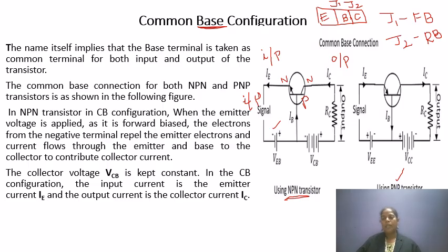The same thing. Here it is P, N, P, a PNP transistor. This side is the forward bias. Positive is connected to positive and negative is connected to negative, so it is the forward bias. Okay, right. Next, the output is the reverse bias. Positive is connected to negative and negative is connected to positive, so it is the reverse bias. So the structure is correct. Clear?